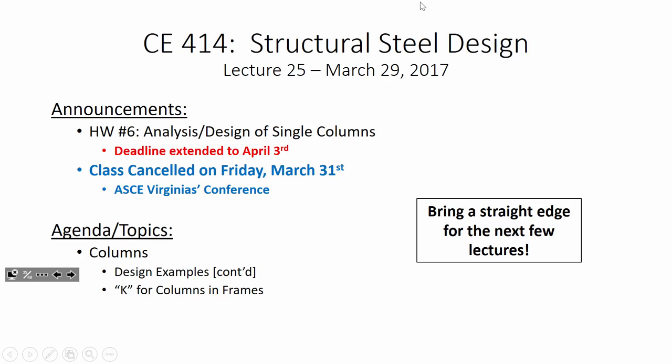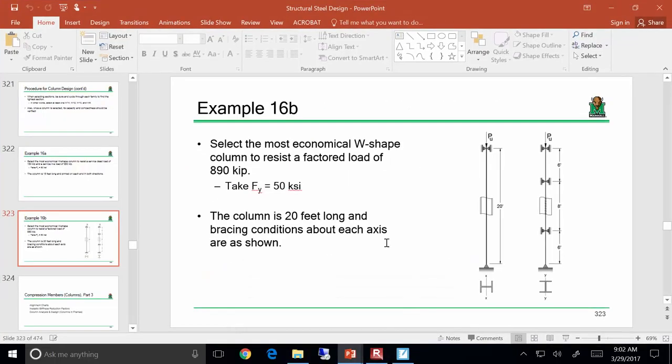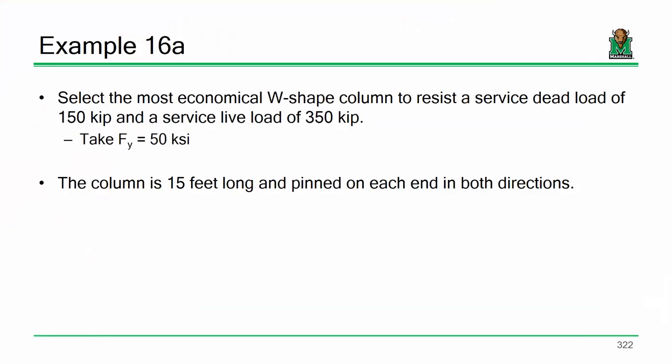Okay. With that, I'm going to shut up and get into the wonderful world of columns. So last time, this is where we left off. We started the world of column design. Instead of giving you a column and determining how much load will cause that column to fail, we flipped it and said, all right, let's handle a problem where you have no idea what the column looks like. If I give you the loads, what column should be selected in order to safely resist those loads. So there's our tenets of column design.